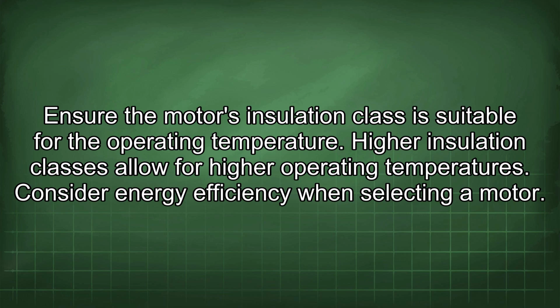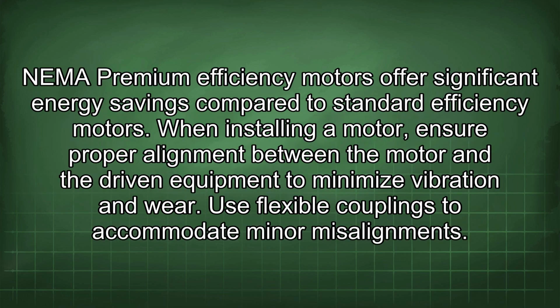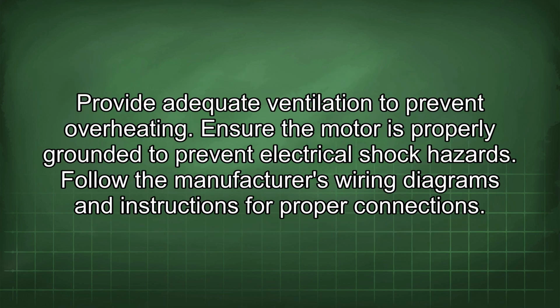Consider energy efficiency when selecting a motor. NEMA premium efficiency motors offer significant energy savings compared to standard efficiency motors. When installing a motor, ensure proper alignment between the motor and the driven equipment to minimize vibration and wear. Use flexible couplings to accommodate minor misalignments. Provide adequate ventilation to prevent overheating. Ensure the motor is properly grounded to prevent electrical shock hazards. Follow the manufacturer's wiring diagrams and instructions for proper connections.